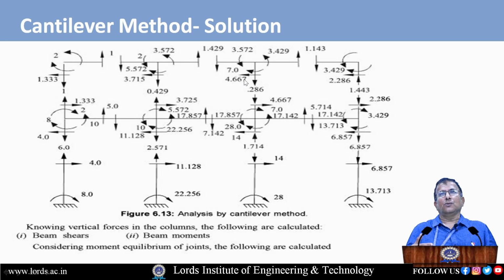This is the process we can adopt to analyze the cantilever frame, or frame by the cantilever method, to evaluate the values of vertical forces, horizontal shear and also the moment induced in the frame. We should adopt the same procedure to calculate these values for the bottom story also. So knowing the vertical forces in the columns, you already know how we can find the values of vertical forces. We can evaluate the values of what we did just now, beam shears and beam moments, by considering the